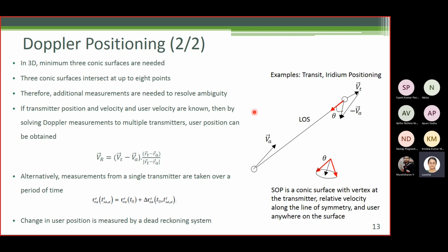I just want to make one more comment. While discussing all these techniques, I think you have got the idea that a good strategy is to combine different methods that complement one another. A good example of such an integrated system is integrated GNSS and INS because they complement each other. INS error grows with time, whereas GNSS error does not.